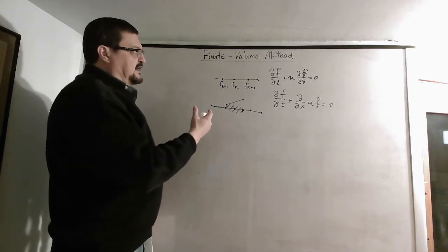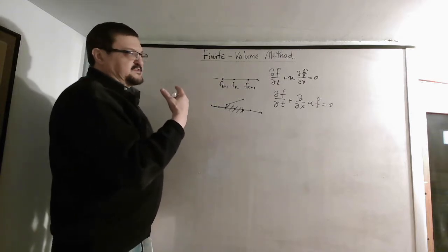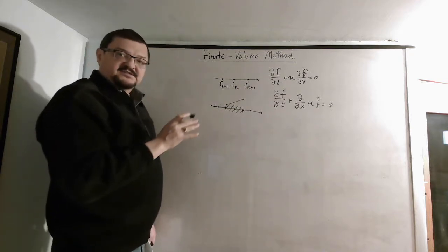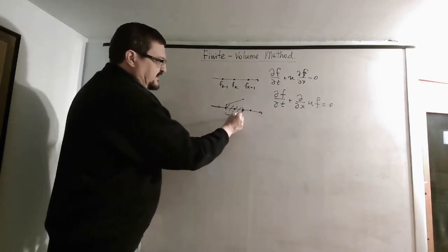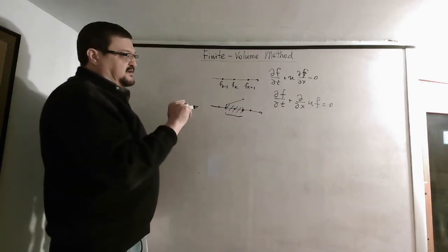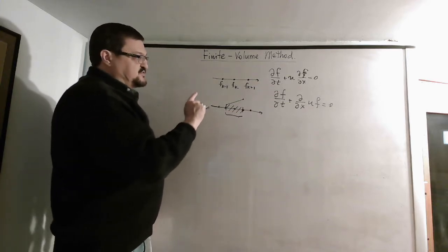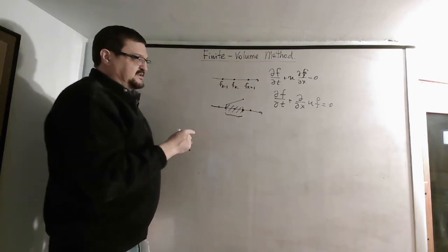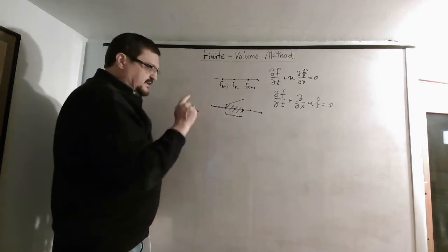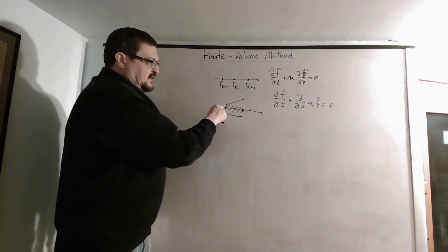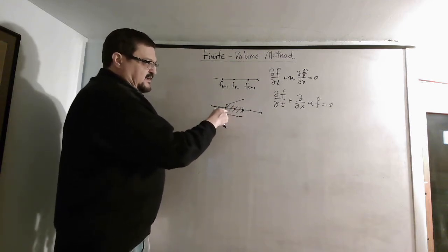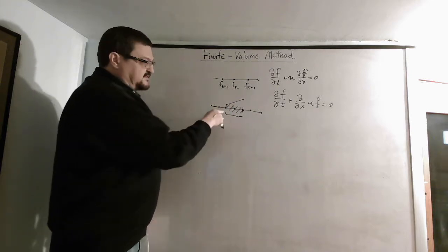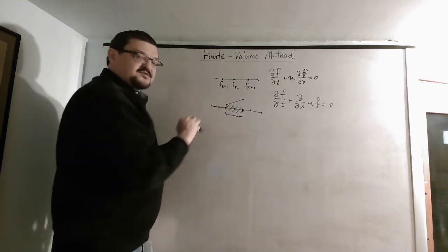So basically, finite difference operates with derivatives, and finite volume switches to integrals over some region or cell, and reduces the problem not to how to approximate derivatives at some point, but to volume integrals and surface integrals of fluxes around the surface that surrounds the cell.